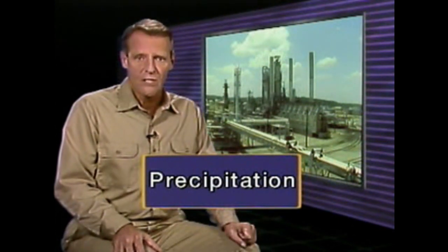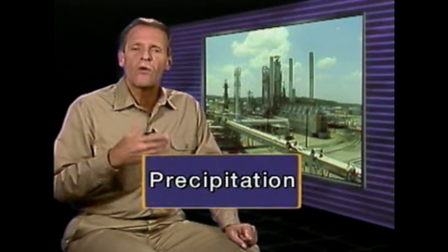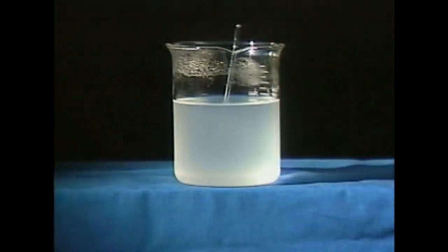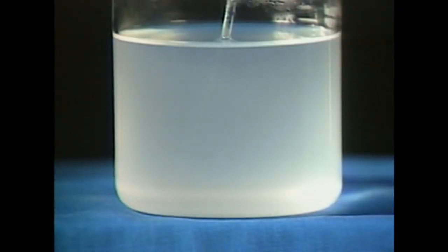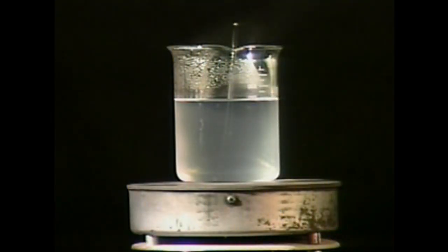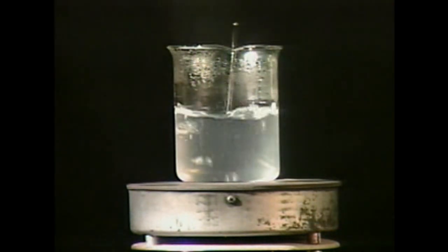If the amount of solids dissolved in water exceeds the amount of solids the water can hold, precipitation will occur. In other words, the solids will come out of solution. Since higher temperature water can hold more solids than lower temperature water, precipitation is most likely to occur when water is cooled. Another physical change that results in the precipitation of dissolved solids is evaporation.